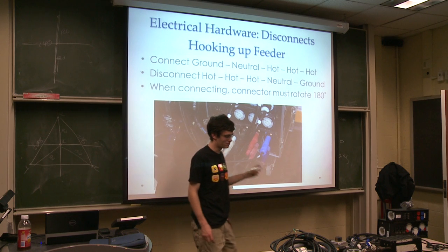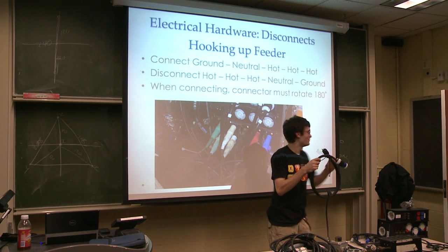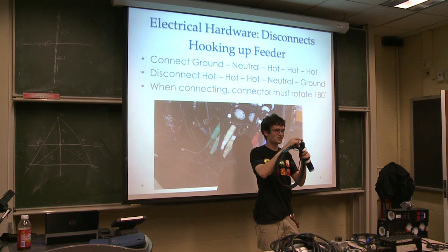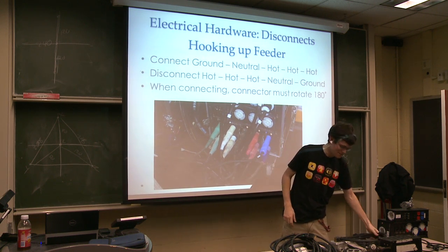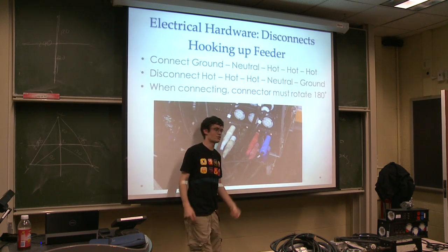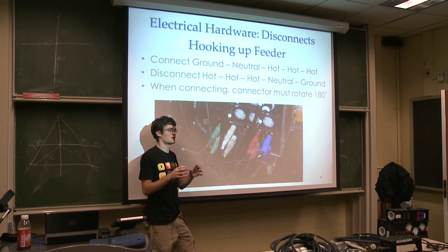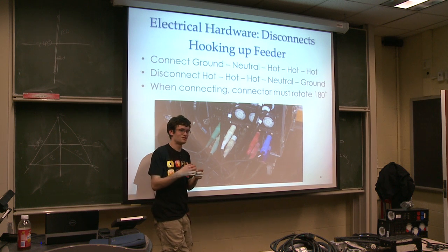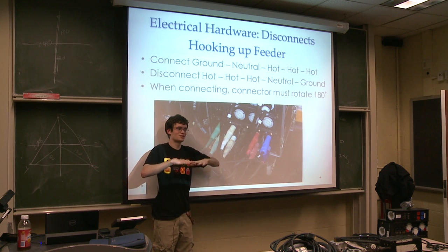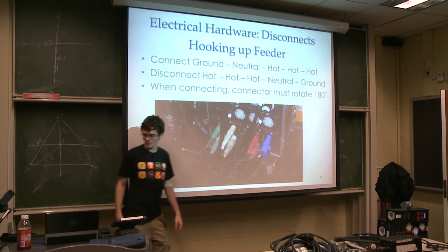And if you pay close attention to plugs, you'll notice that often the ground pin is slightly longer, because this actually enforces this convention on every single connector. It forces the ground connection to be made first, followed by the neutral and hots. This is in case there is a circuit happening with current flowing through it. The hots get disconnected first, and therefore the plug is still in the receptacle and ground is still established to prevent danger. Also, while plugging it in, the grounds can connect and level everything before the hot gets connected and the voltage is applied.